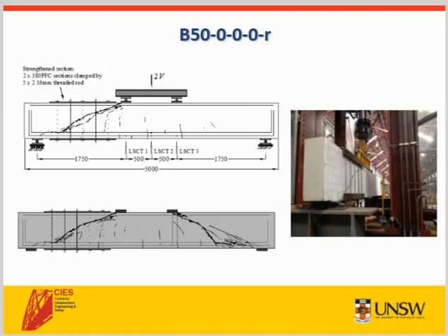So we decided to clamp the damaged side, pre-tension some threaded rods with some load, and then test the other section of the beam. The second failed side gave us a result we were originally hoping for, and we noticed that the number of fibres in the originally failed side was significantly lower than expected. This highlights the fact that even in well-controlled environments such as in our lab, we may still violate our assumption that the fibres are well distributed within our samples.